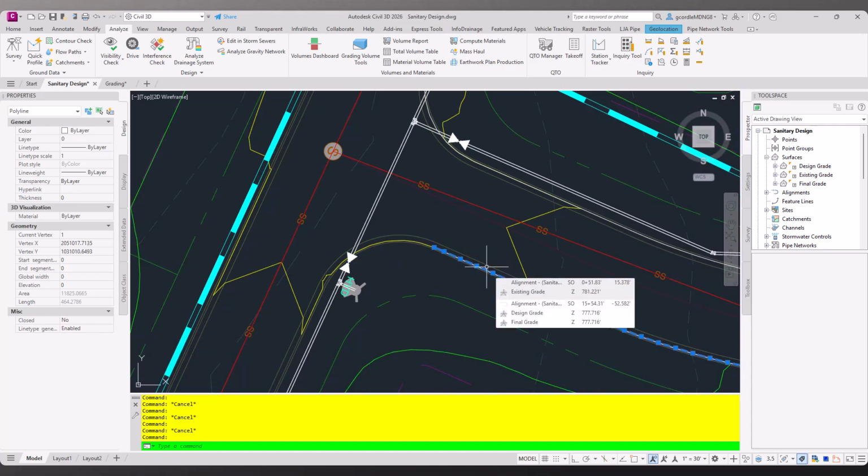We can dig down into the surface a little bit more. Or we can add in a single wing catch basin to catch as much of that water as we can, or a double wing catch basin, whichever one. Or a grate inlet if it is not that much water flowing to it, and then tie it into our system all together. So now we can really utilize the flow path water drops to analyze the low points of our design to then determine what we need to do, both analyzing existing catch basins and proposed catch basins.